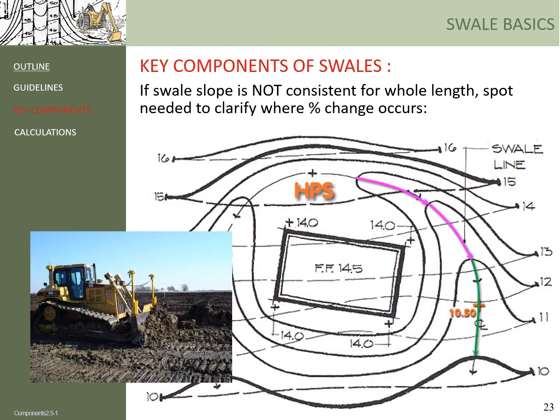As we have been saying, the spot elevations control the construction, not the contours. In your professional careers, contours will probably come to mean less as automated construction methods take over manual methods. GPS and laser control construction equipment, such as bulldozers, graders, and scrapers, are already in service and work from 3D landform data that can control the tilt and depth of a cut or fill and provide real-time location information for the operator who just has to control speed.